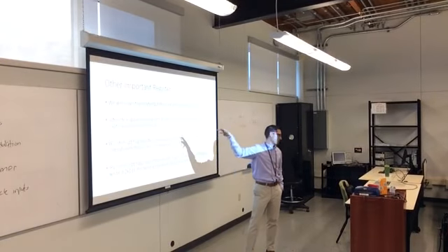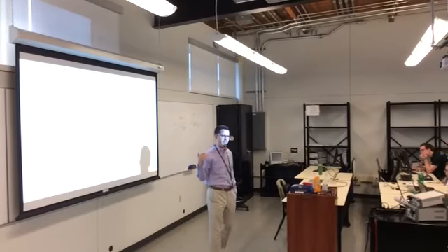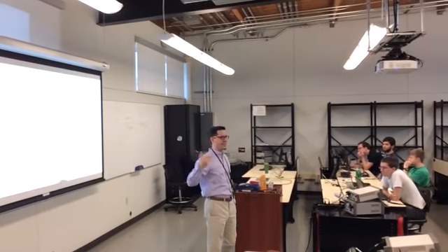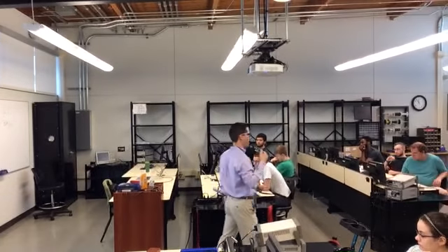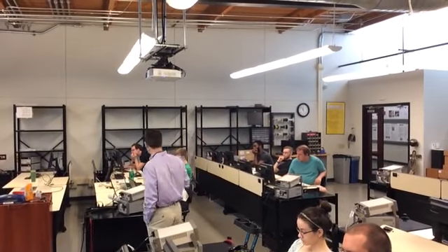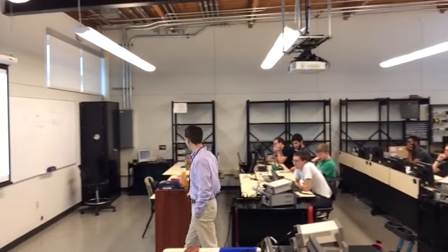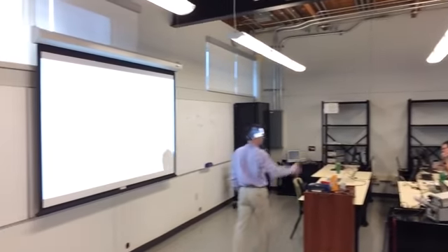There is also an interrupt flag register. The interrupt flags tell you whether some interruptible event has occurred. That is independent of whether the interrupt is enabled. Even if the interrupt is disabled, the flags will still get set. So if overflow occurs, but you don't have the overflow interrupt enabled, the overflow flag will still go high.